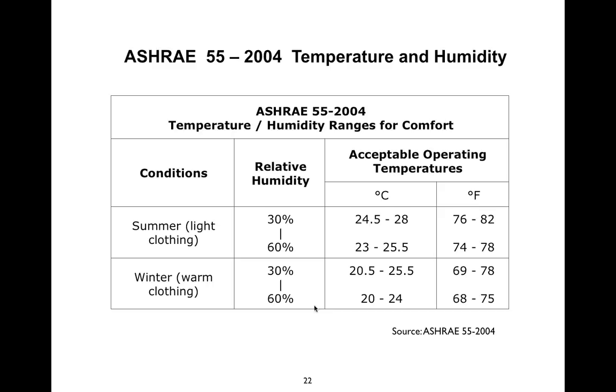well, if your windows are open, remember you're still bringing in cold air and heating it up. So you're probably not helping much. What might help is buying a humidifier or maybe putting a pan of water on the radiator or something like that, so you're evaporating some water. You boil a pot of spaghetti, that's going to throw water into the air. So you need something. The air brought in from the outside is already dry because it's a very low temperature outside. When you bring it in and warm it up, the relative humidity, and relative means how much humidity it can hold, drops even further.